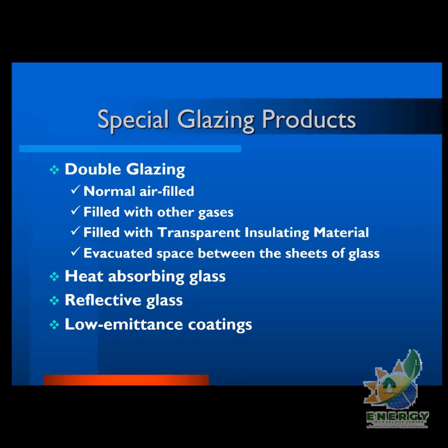Or, because if you have air inside, air can absorb the heat, and then as it moves and hits the walls of the glass, the heat will be transmitted through to the outside or to the inside. So it's also possible to evacuate the air so that you have a vacuum, so that you reduce the heat losses in that respect. So you reduce convection heat losses.